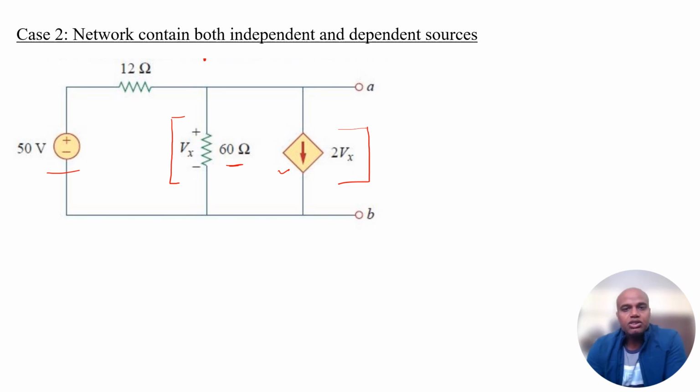Method 2 says that we can put a short circuit over here and then find this current ISC. And of course, to get the Thevenin equivalent circuit, we have to obtain the VTH. Therefore RTH becomes equal to VTH upon ISC. So this is method 2.